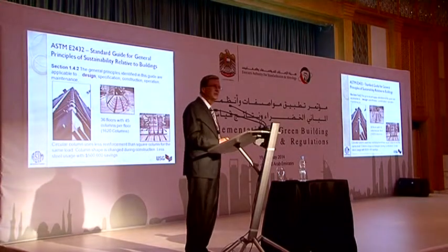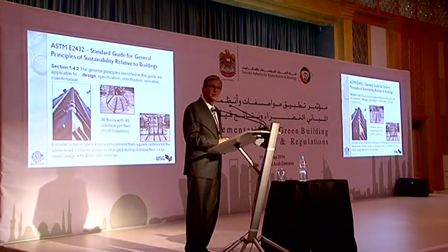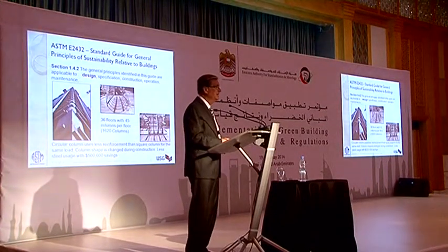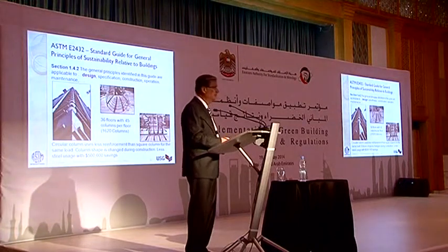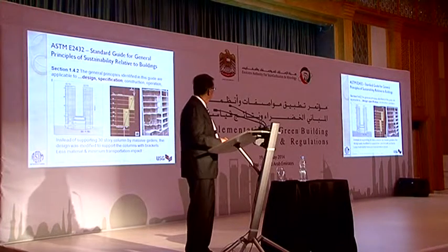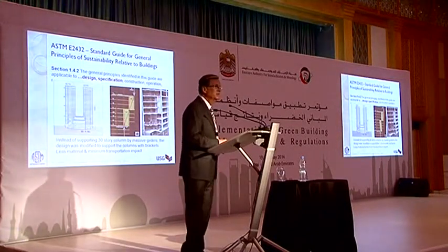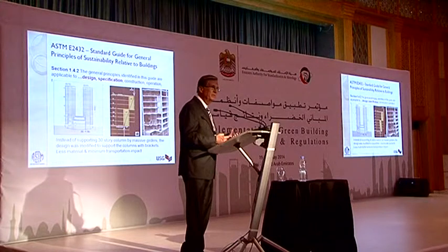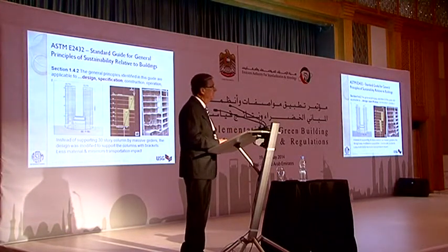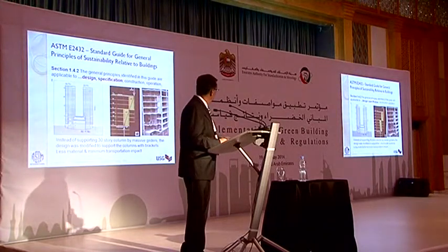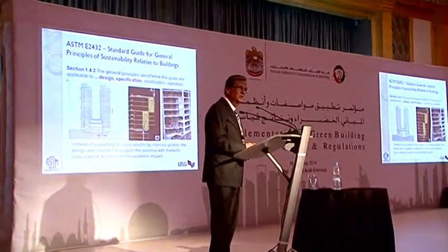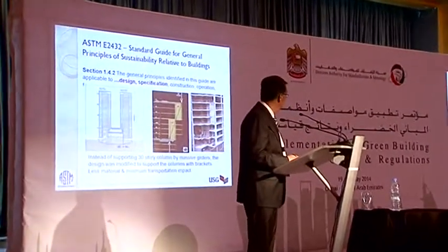There was a $500,000 savings that accrued to the owner, but more than that, there were a number of impacts in terms of materials saved and the corresponding impact on other environmental aspects of those materials. In the same review, the building had been designed to use some massive steel girders to support some 30-story tall columns, and it was determined that this could be done by designing some shear walls that were constructed on site with concrete and reinforcing.